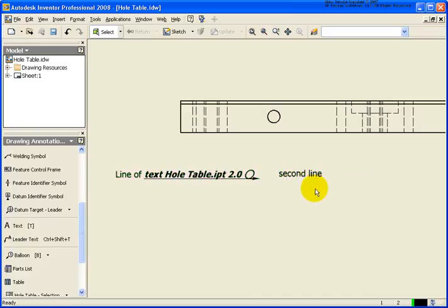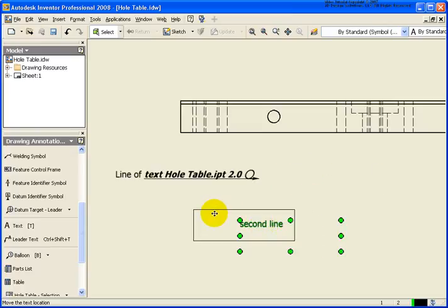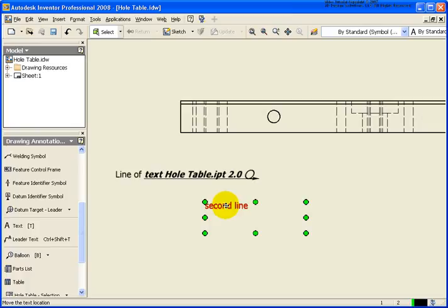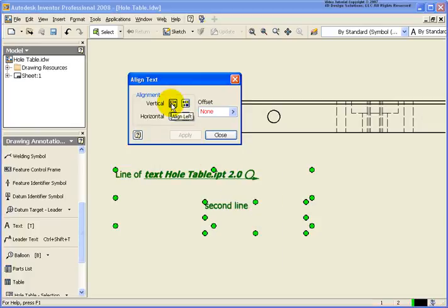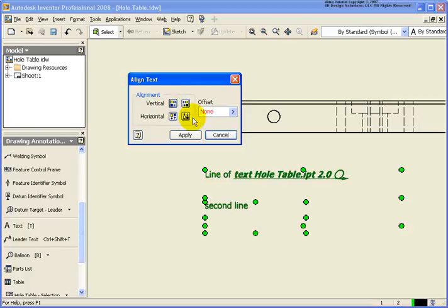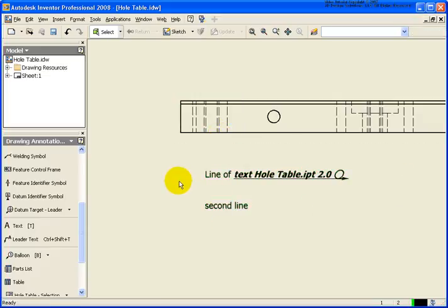So there is no constraint that's applied. So I can still freely go back and move them around. It's just an alignment option. So in this case, let's go back and align the second one to the first one. In this case, let's do it vertically. So you can see definitely it has preference there. And there was also an option for an offset if I wanted to have one offset in from the other. We're able to do that.